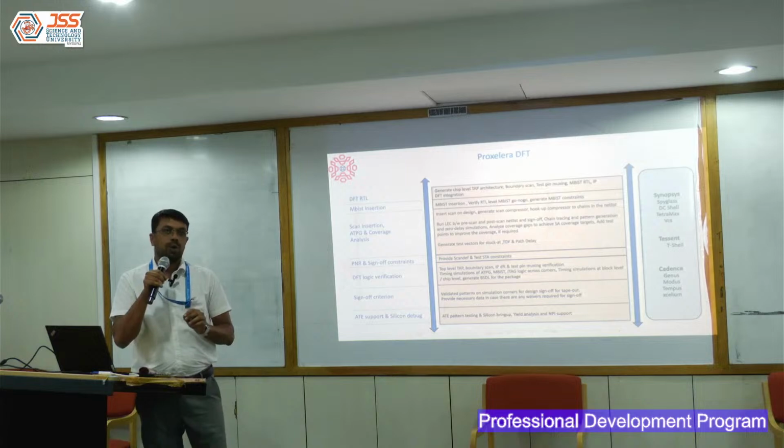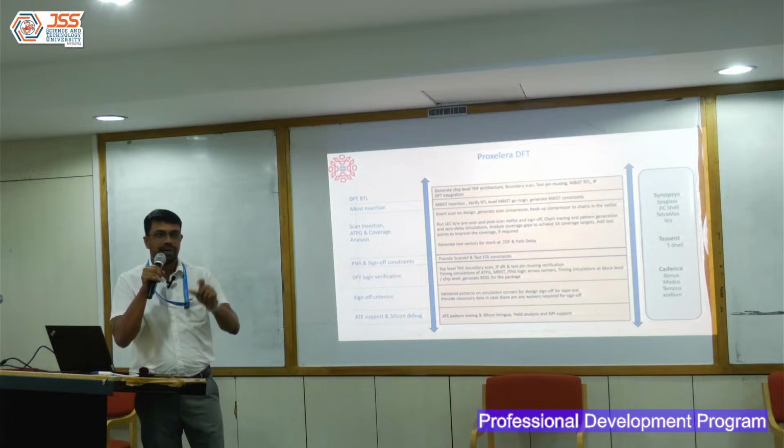So during this process, there can be a lot of manufacturing defects that can get introduced into the chip. So when I am shipping the parts to my customer, I want to ship only good parts. I don't want to ship any bad parts to the customer, because he is not going to do any testing immediately. He is going to put that component onto the board, and then he's going to do a board bring-up. And at that time, if he figures out that it has been a faulty chip which has been put on the board, he will have to completely discard the board, and that is going to cost him.